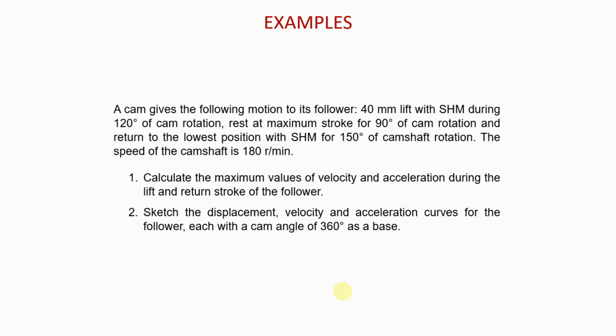And now they want you to calculate the maximum values of velocity and acceleration during the lift and return stroke of the follower. And then after that, you have to sketch the displacement, velocity, and acceleration curves for the follower, each with a cam angle of 360 degrees as a base. Now this is more like an exam type question. I will show you how to do that, and you will find that it is not as difficult as it may seem right now. If you need to pause the video just to look at the question carefully again, you are welcome to do that, but we will move right along.